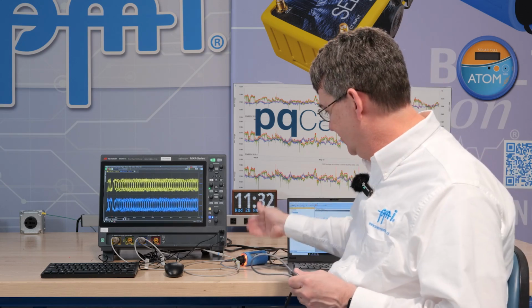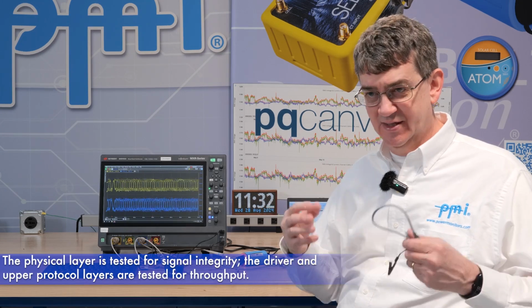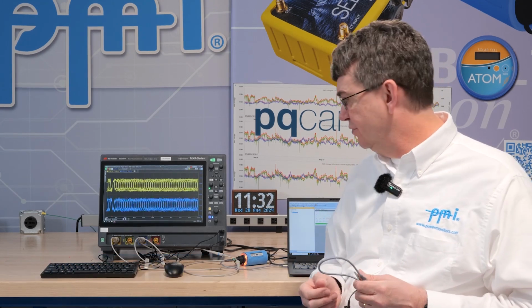So we're going to be testing the physical layer interface of the Bolt to make sure that the controlled impedances are correct. There's no impedance mismatches along the path from the circuit board all the way into the laptop. And we're also going to be using an eye diagram to judge signal quality. And then we're going to be testing the driver and the upper layers of the interface to make sure that the throughput is what we expect through this high-speed port.